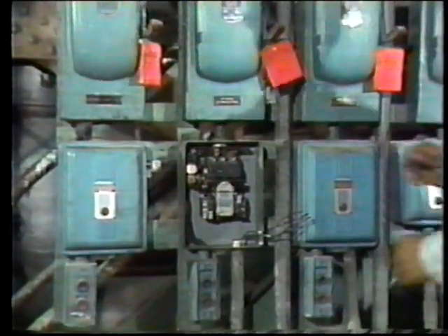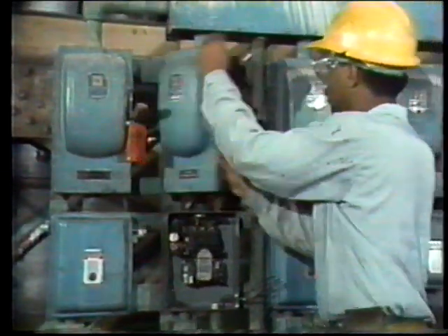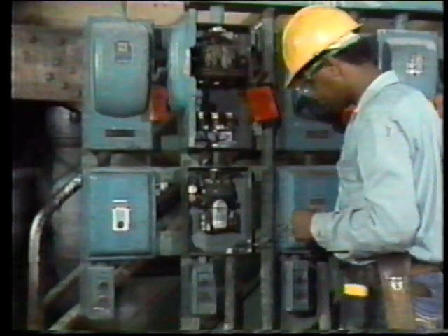Well, you've just seen a typical termination procedure on a piece of low-voltage equipment. To complete the job, Bill has to terminate the remaining ends of the conductors to the contactor at the other end of the conduit. Before he starts those terminations, however, Bill is going to double-check to make sure that the contactor has been de-energized. You can see that the equipment's been tagged out. The switch is in the off position, and the fuses have been pulled. Using the same procedure as before, Bill will check the contactor with his voltage tester, phase to phase and phase to ground, to make sure it's de-energized. Once he knows it's safe to work on, he'll go on.